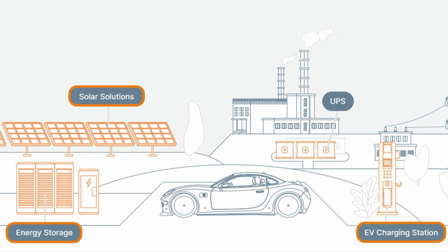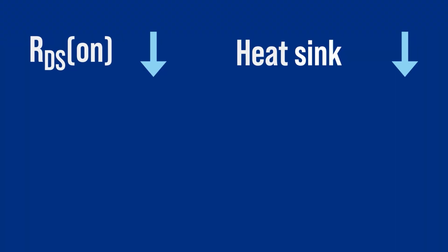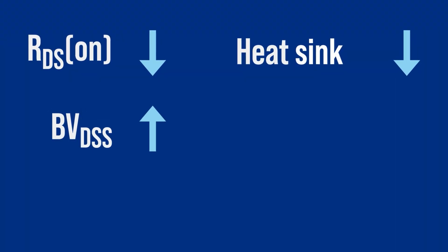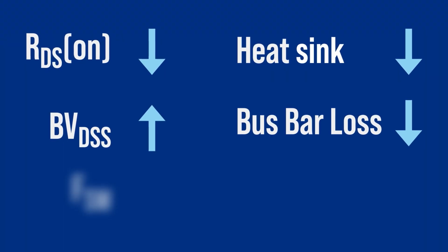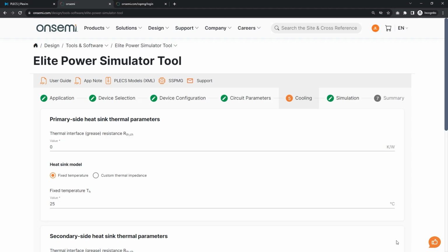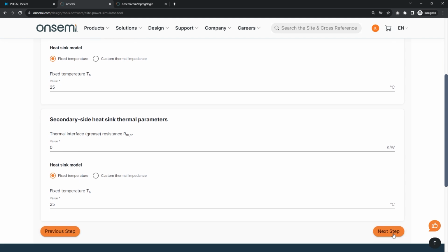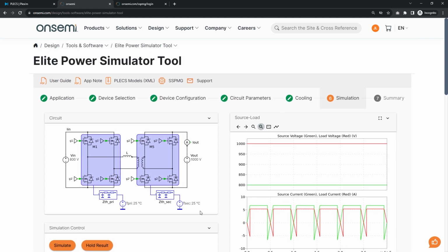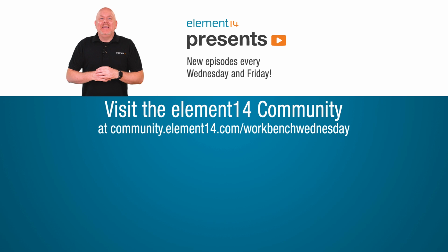In review, a silicon carbide MOSFET is a MOSFET with some unique capabilities. When working with multi-kilowatt or megawatt converters, their high breakdown voltage, low RDS(on), and fast switching can mean more efficiency and less overall cost for a system when used in a high power converter. Check out the design tools that onsemi provides for their components so that you can fully evaluate how they would work in your design.